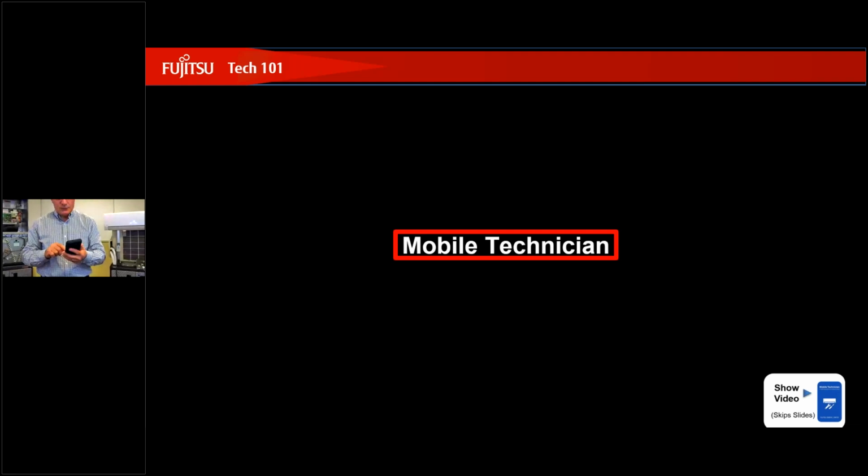Because on occasion, you will run into a situation where the unit's not operating correctly. It'll come on, it'll ramp up, go through a cycle. The next call for either heat or cool, the unit will cycle up and cycle right back down again, and will not throw an error code. That could be that I'm low on charge. I've got too much temperature on my compressor and the unit's actually trying to protect itself. But that won't give you an error code. So the PT chart on this mobile technician, very, very important.